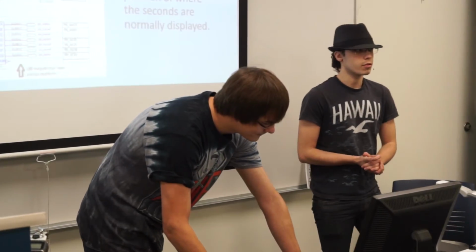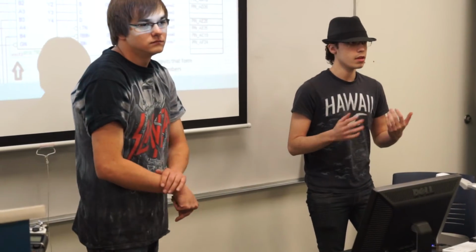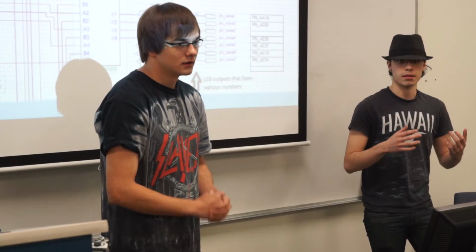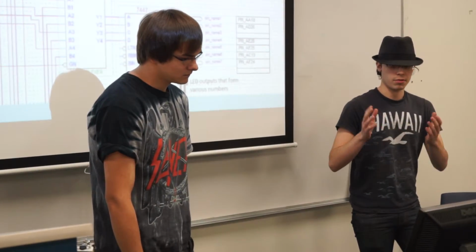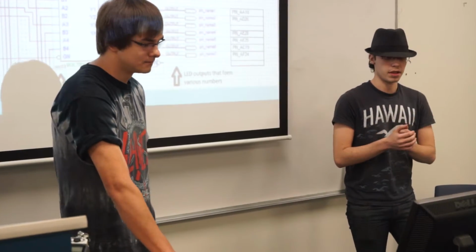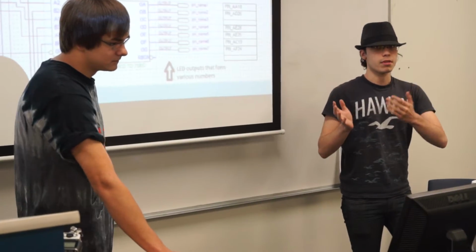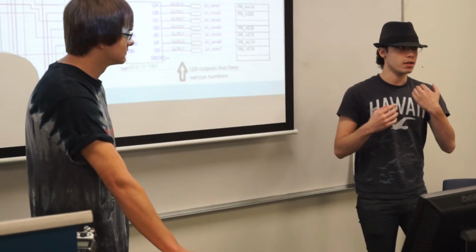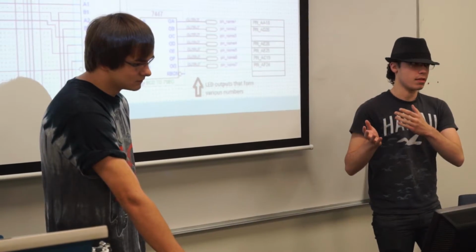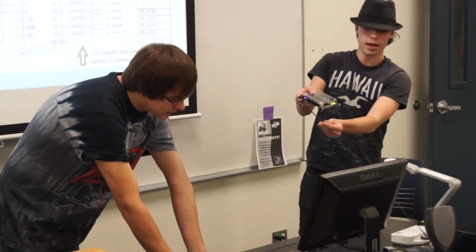Going forward from that, after we had made our clock pulse reliable, outputting a 1 second signal, we were able to add in our multiplexer. The output signal was tied to a BCD segment driver, outputting the binary of 1 up to 9 and keeping track of that in the BCD segment driver, which is our 1 value here.